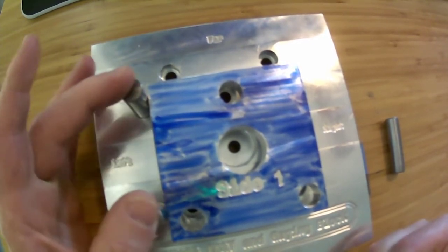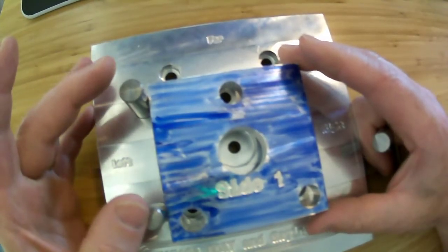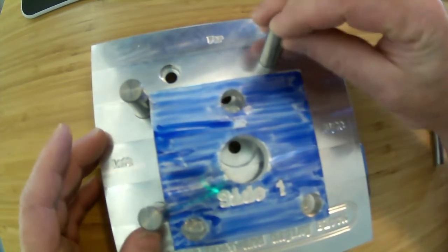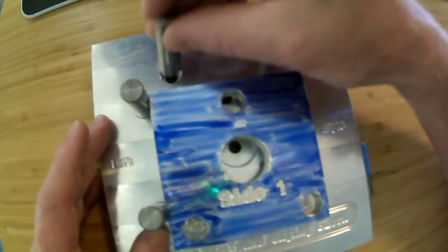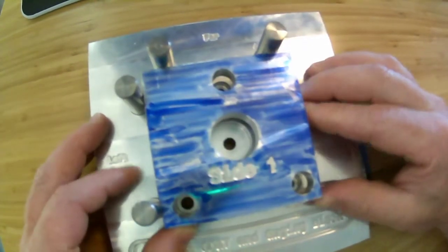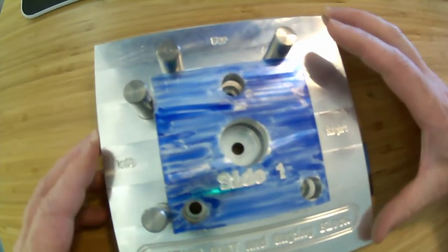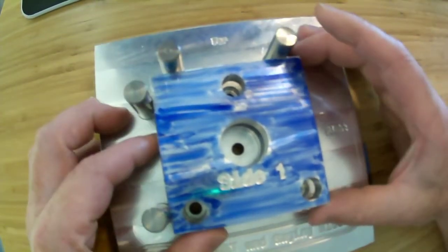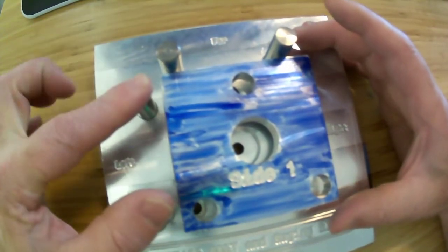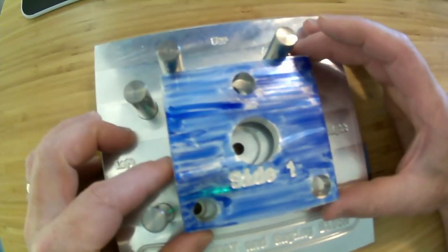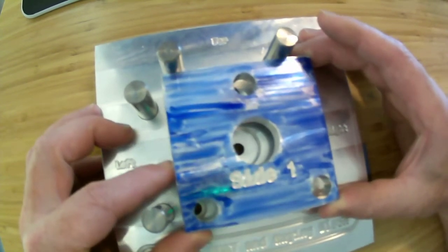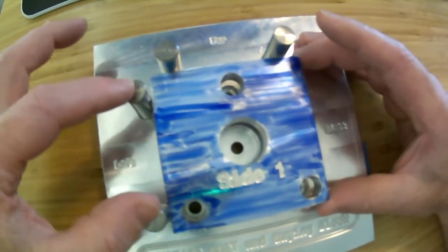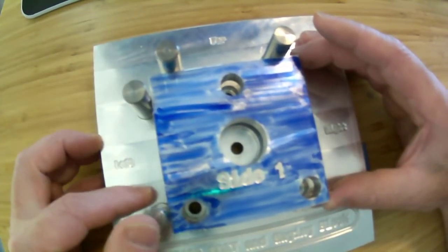When I wanted to eliminate movement along a direction, I put in 2 pins. So what happens if I do that and I put in 2 more pins? Well, the problem is I've now over-constrained it, because what do these 2 pins do? If I moved the part off of these side locators and just thought about these locators on the end, I limited movement in Y and rotation around Z. But remember, I already eliminated rotation around Z over here.